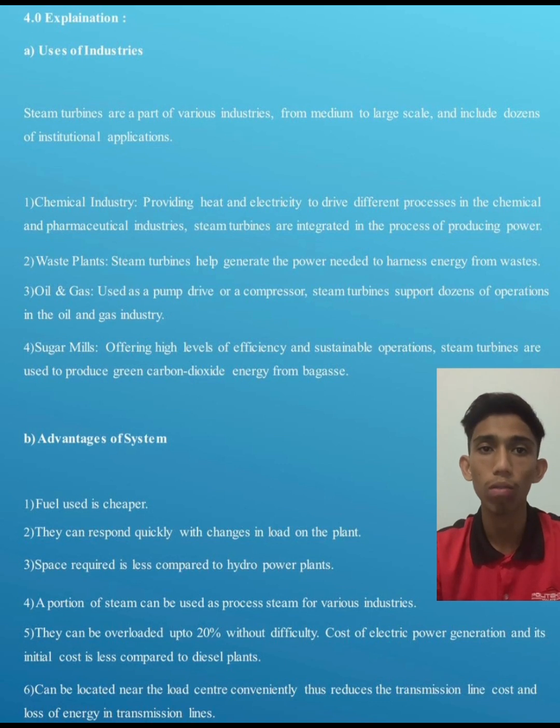They can be overloaded up to 20% without difficulty. 6. Cost of electric power generation and its initial cost is less compared to a diesel plant. 7. Can be located near the load center conveniently, thus reducing the transmission line cost and loss of energy in the transmission line.